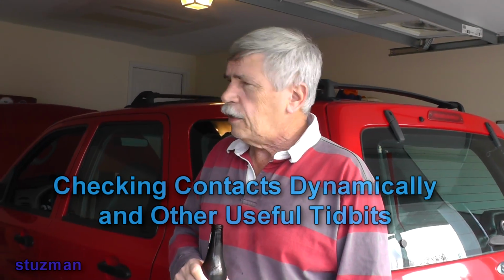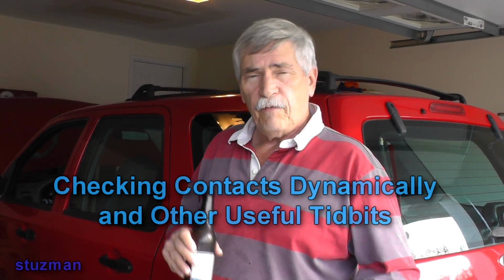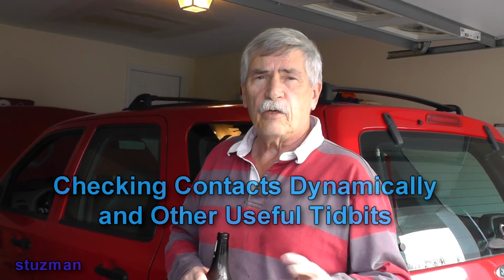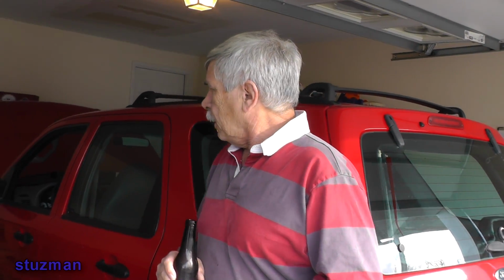Alright, welcome back. We are going to look at some final tests on this Escape with this fuel pump that you may or may not know that I went ahead and replaced. Now in this video we're going to be talking about checking relay contacts, and it's not using an ohm meter, which is not really the best way to check contacts. With this method you can check relay contacts, switches, pressure switches, doesn't matter. The only thing that does matter is you got to know the current is going through this switch, and we're going to verify that too.